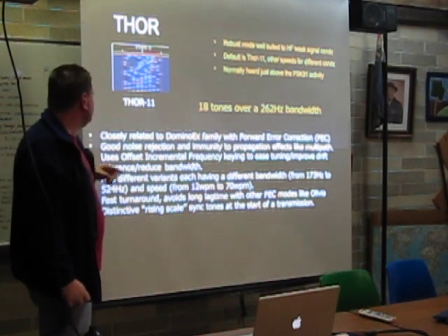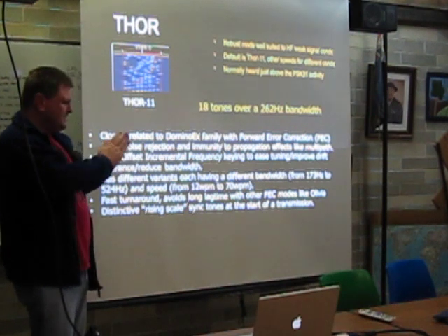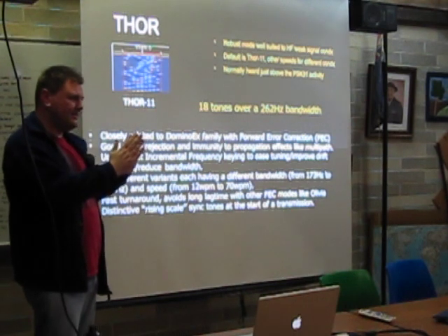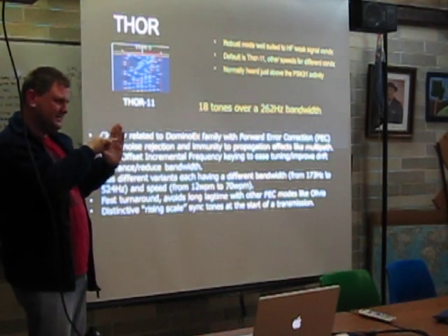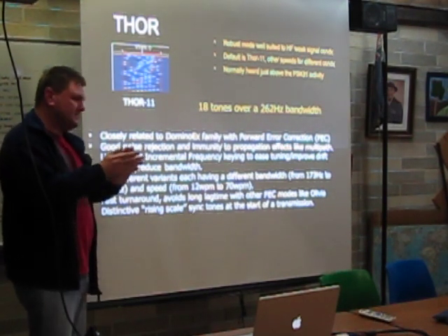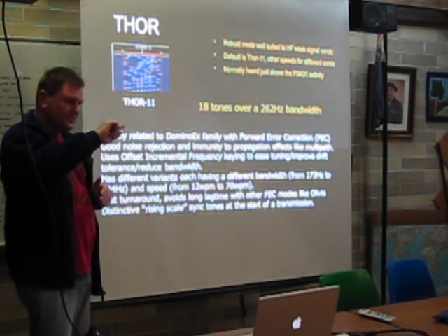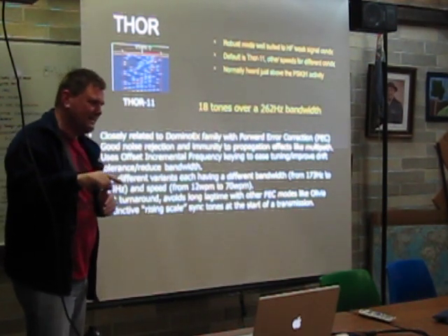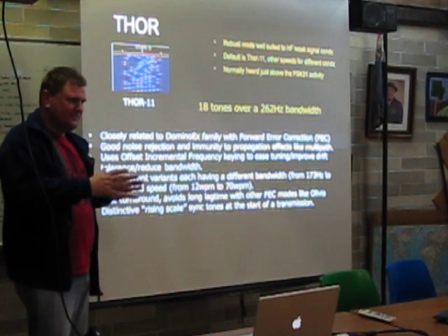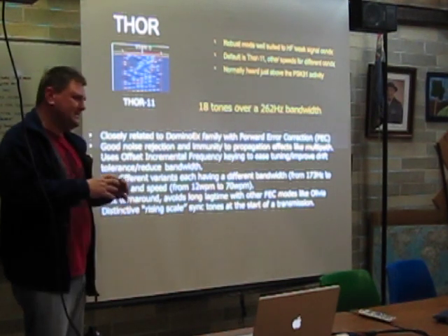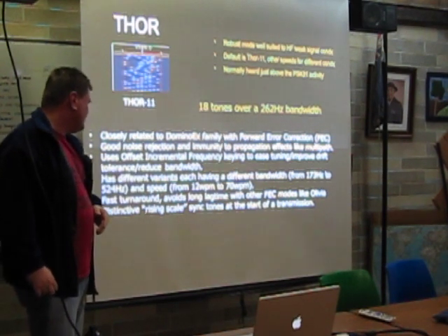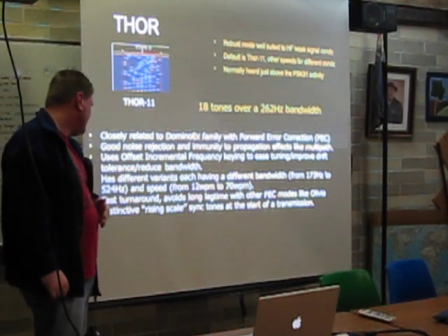But the advantage of this one is that it doesn't use the exact tone to encode the binary ones and zeros. It uses the difference in tones, a sort of delta. And what this means is it makes it very immune to drift. You can even be turning your VFO knob while the signal is playing, and the computer will still be able to decode what you're saying. So the frequency stability requirements for your radio are a lot less for this particular mode because it uses this differential frequency shift keying.